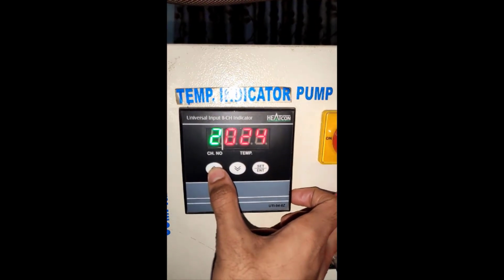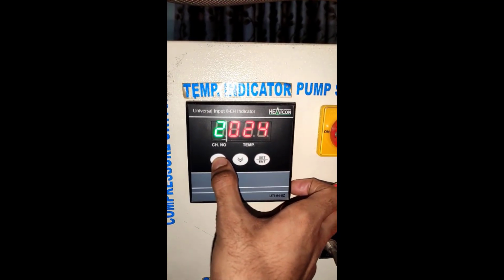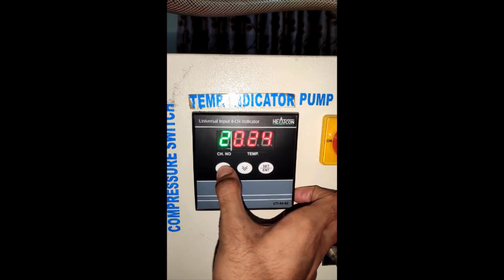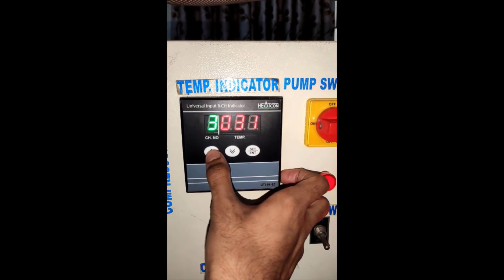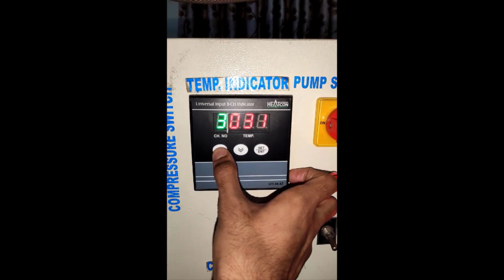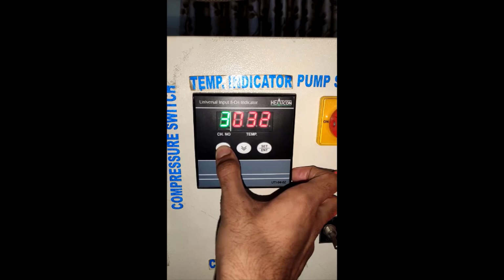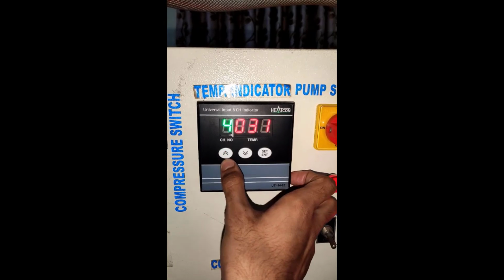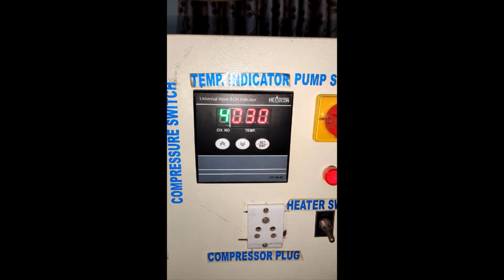Okay, so this is how you can find out the temperatures. This will indicate the different locations. The 1 and 2 will be indicating the temperatures of wet bulb and dry bulb temperature at outlet, and 3 and 4 will indicate the wet bulb and dry bulb temperature at an inlet. So as you can see, we have to actually allow this to remain steady at somewhere around 20 seconds, so that we can obtain exact temperatures.